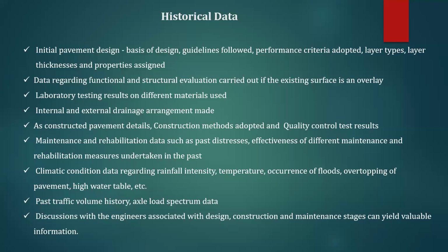Axle load spectrum. So what type of loads are coming? Whether only tandem and tridem axles are coming. This axle load spectrum is very much important to estimate the vehicle damage factor. You know VDF in flexible pavement design in IRC 37, 2012 or 2018 or the basic 2001 version. So for calculating MSA, VDF, the vehicle damage factor, is very much important. So we have to take that axle load spectrum. We have to conduct this axle load survey in the field, using the weighing pad, you have to get the data, analyze it, and finalize the VDF value, vehicle damage factor.